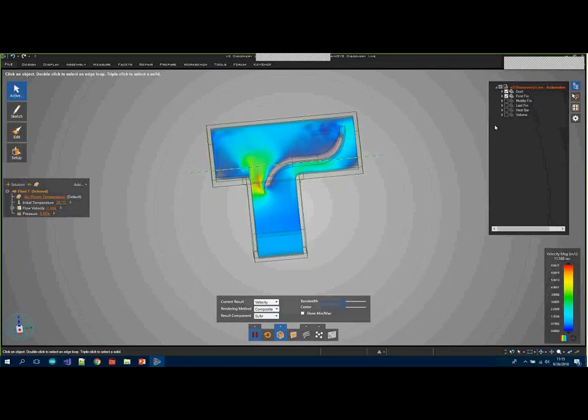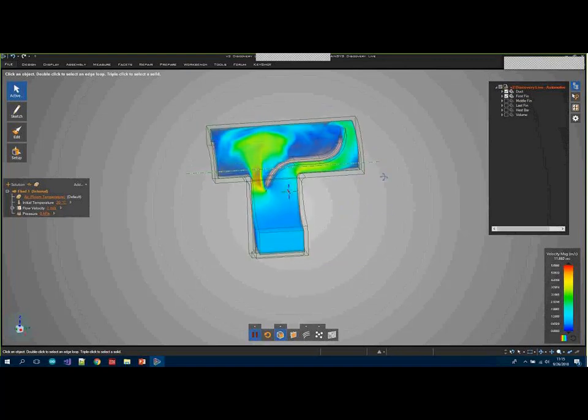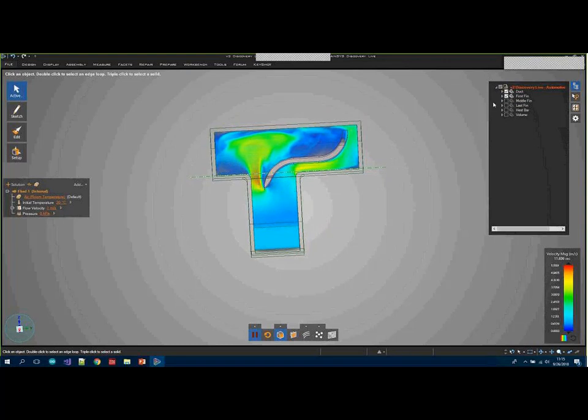What we can see, as soon as I activate that, if I shut off these results, you can see the fin inside there. But as you note, as soon as I turn that on, the volume of the airflow updated instantaneously. And so now we're continuing on with this analysis. I'm going to reset the simulation just so we can get an idea of what's happening here. You can see the amount of time that has elapsed within the simulation from the legend. So, of course, it's going to be a little bit slower than real time, but you can see it here.